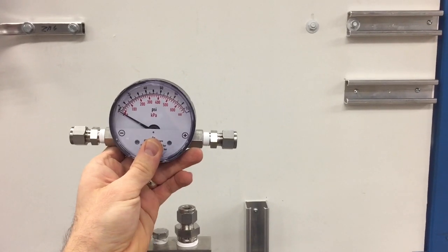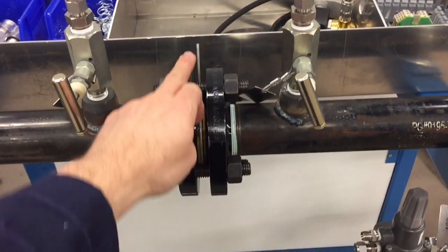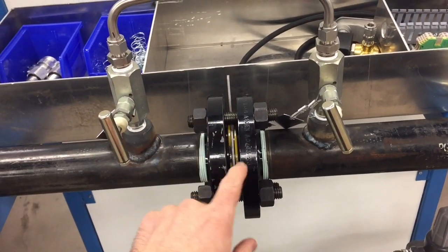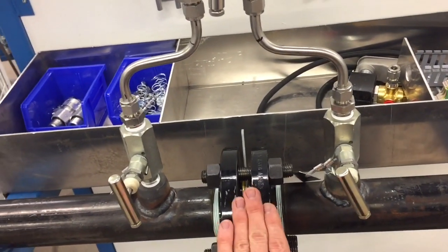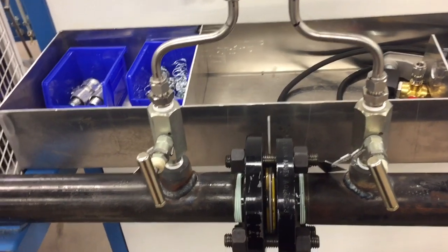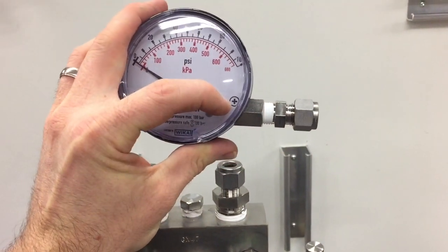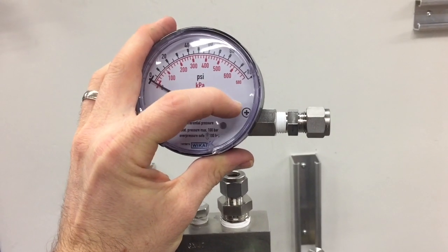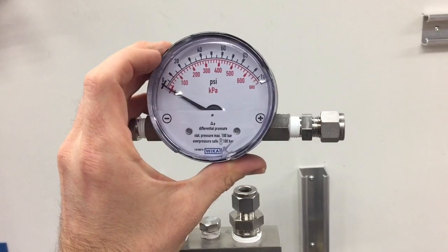The plus side on the gauge over here on this side needs to be upstream of the orifice. So if you look down here, we have an orifice plate here in the line. It's a restriction, about 1/8 of an inch diameter, and when gas flows across it, it's going to create a higher pressure upstream because we have that restriction, and a lower pressure downstream. So looking at our gauge here, this plus means to represent the higher, the more positive pressure. Sometimes it'll also be indicated with an H for high and an L for low side.